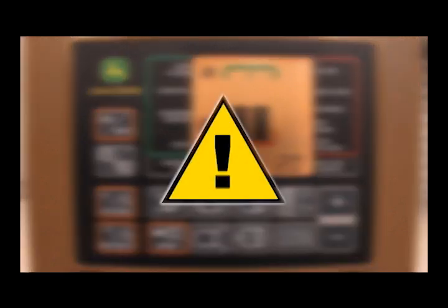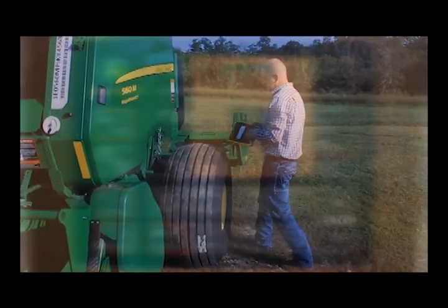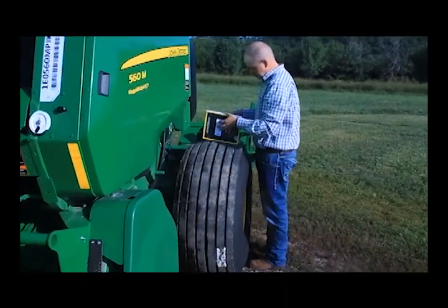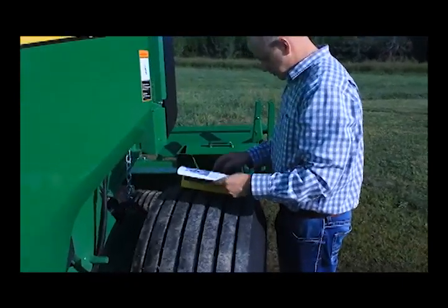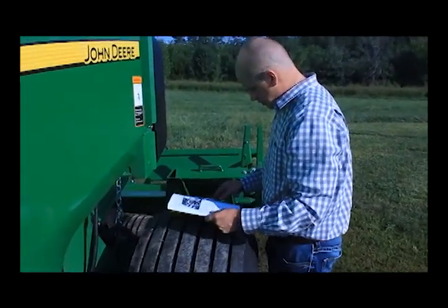Note, balers equipped with a pre-cutter pickup must add at least 1 additional layer of net wrap when baling. Also, we do not recommend running less than 2 wraps per bale. Refer to your operator's manual for net wrap settings when running at less than rated PTO speed without speed compensation.